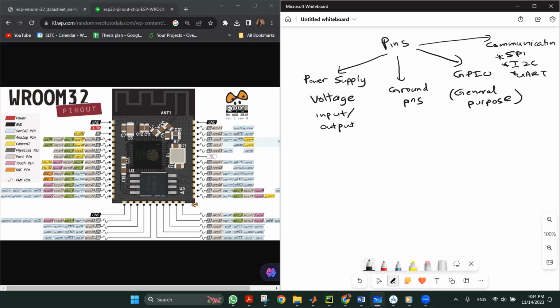If we are sending data over SPI, then we define certain parameters such that the transmission happens in a specific manner. The bit transmission follows a specific clock frequency. It follows serial communication, and then other parameters are defined. Based on that, the receiver will know this is the frequency of receiving the data, and based on the other parameters, the receiver is able to cut off the data appropriately and decode the data from that received data stream.